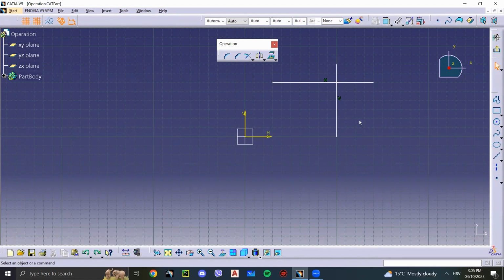So let's Control Z and try this again. Press the first one, the second one. Keep our mouse here. Press Tab to select radius. And now let's select 40. And there we go. Notice how we lost these lines. That's where these options come in.